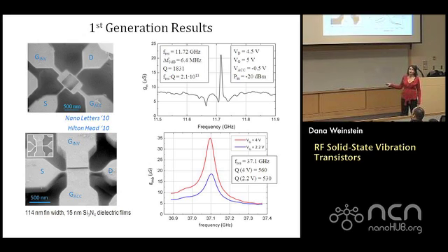And the reason we weren't able to detect frequencies higher than this was because the FT of the transistor, which is a crappy transistor, we built it in-house, remember? 15 nanometers of silicon nitride gate dielectric, W over L of like half, okay? And someone etched Pyrex in the tool prior to it being used to etch the device layer. Extremely shameful. The reason we couldn't do that is because the FT was 40 gigahertz, right? So if you get better transistors, higher gain transistors, higher FT transistors, you improve the performance of the device.